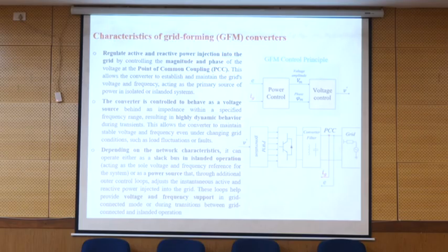We said that we don't need a PLL, but in reality we should consider the voltage and frequency of the grid for the grid forming converter. Does anybody know why? We can say that we provide power based on the voltage and frequency we need, but now we can say that it is based on the point of common coupling. Common coupling means the point where the converter is connected to the grid. Does anybody know that there is some contradiction? Does anybody know why?